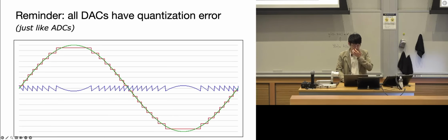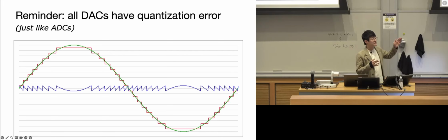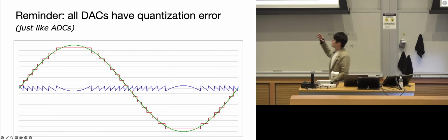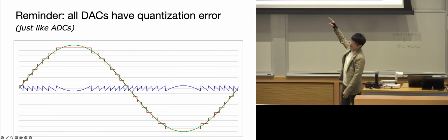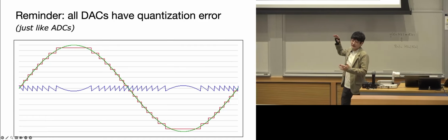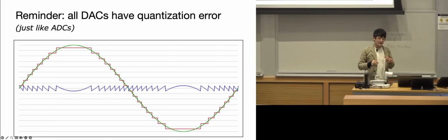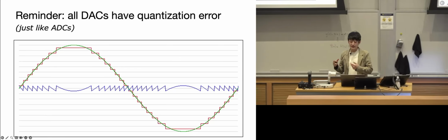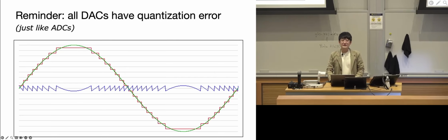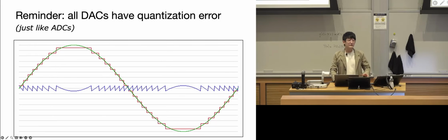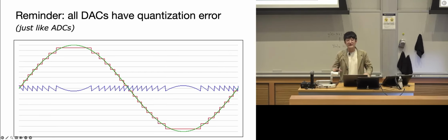And another thing to realize, just keep that in mind, is that similar to the ADCs, all these outputs from the DAC also have this zigzag, step kind of shape. It just depends on how many bits you put onto this DAC. Okay. Any questions for the few types of DACs that we showed? 4 types, but the latter 3 are working on similar principles.